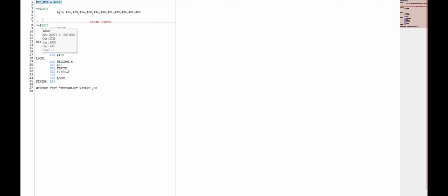And we'll start off here. So that one is jumping to start. That's handy when we're creating our little subroutines that we don't want to run at the start of the program. And we've got here jump to subroutine switch. So this is essentially how we jump to our little subroutine to switch the memory bank.